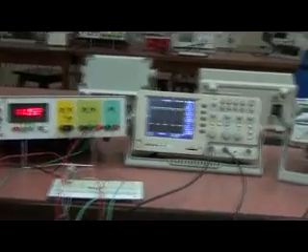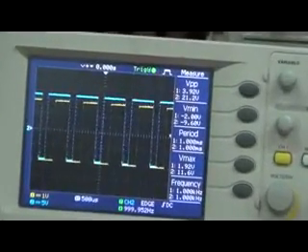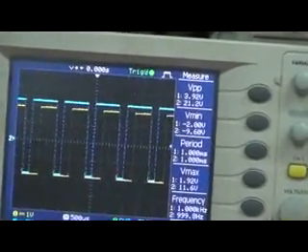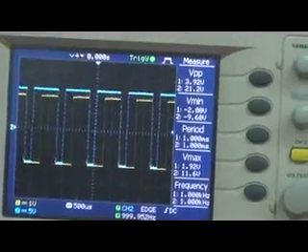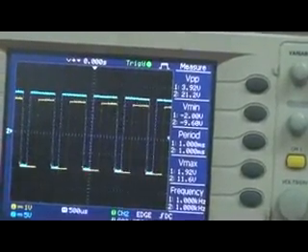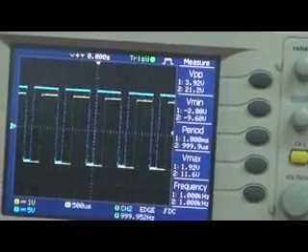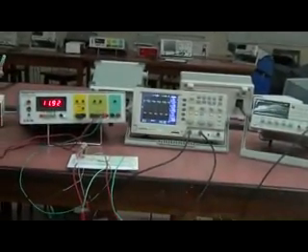The input signal is a square wave, which we can see through that the yellow line shows the input signal and the blue line is the output. That is, it is giving a small pulse output and returning back to its stable state. The pot or the potentiometer that we are using in the circuit can be used to vary the width of the output pulse being generated.